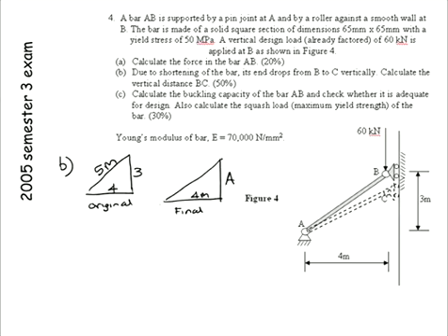Now this length here, our member was originally 5 metres long. It's carrying a compression force of 100 in it, so it is shortening amount PL on AE. Based on that P being 100, I'll write it as kilonewtons. So this is where you have to get the units right in here. So therefore, this new length in here is 5 minus delta.